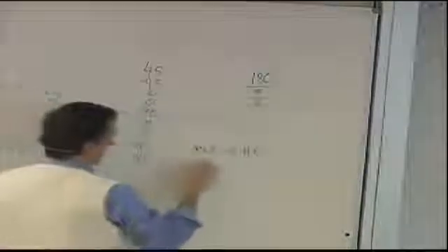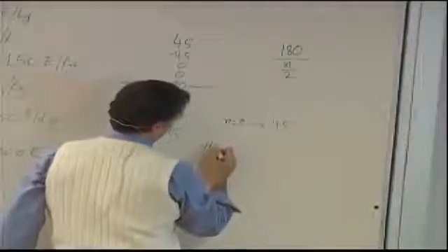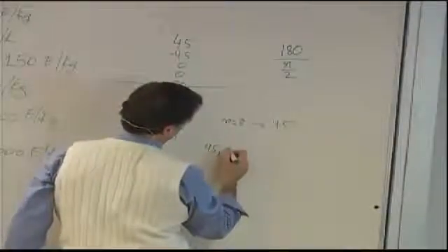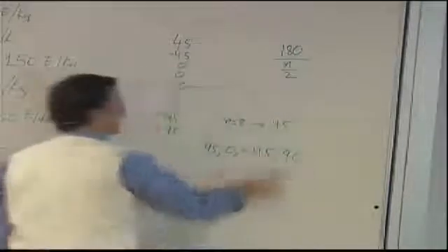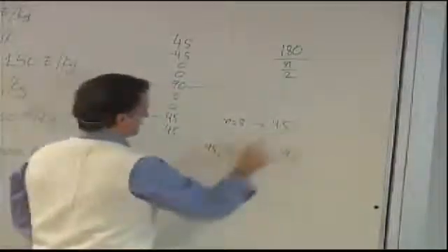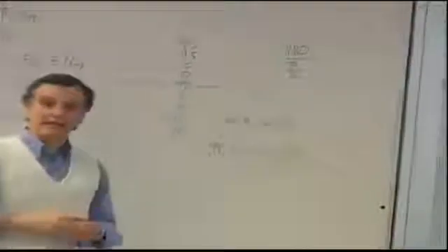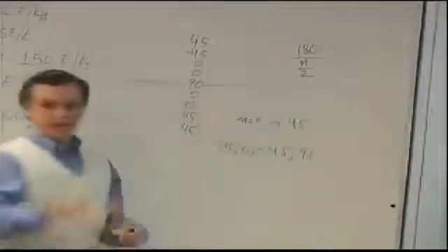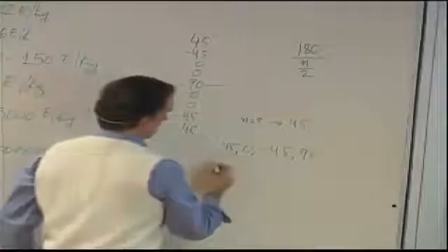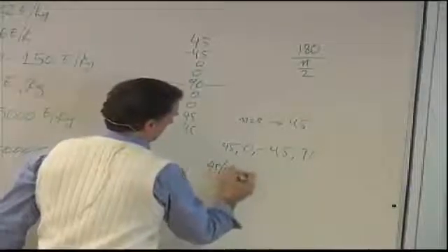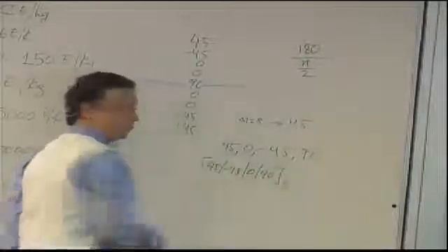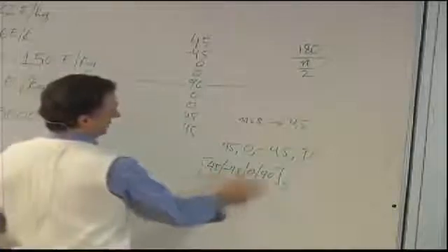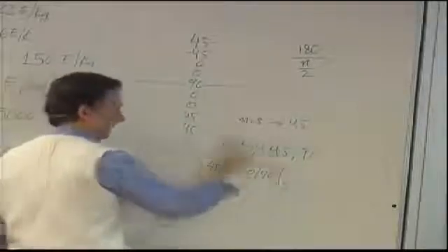So you need to start from 45, then the next one would be 0, the next one is minus 45, and the next one is 90. Basically, those are the only angles that appear in multiples of 45 that will satisfy this. So a symmetric laminate that uses these in any combination or any order would be quasi-isotropic. So 45, minus 45, 0, 90, symmetric, is quasi-isotropic, but so is any permutation of these angles, 45, 0, minus 45, 90, and so on.